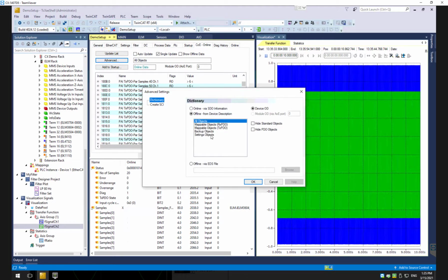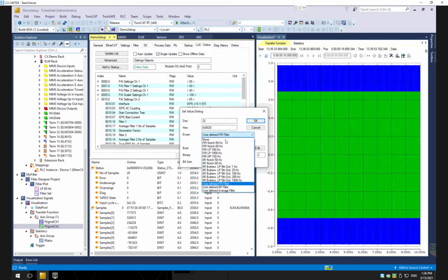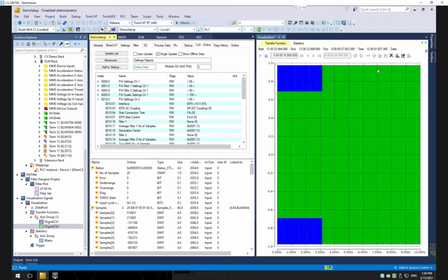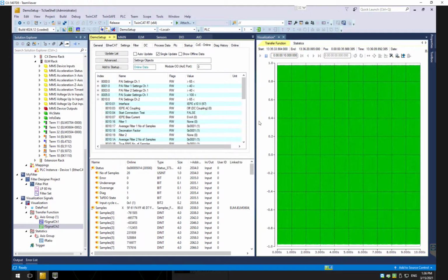We'll then go to the second channel and set the actual filter, which is now set to user defined, to 0, no filtering, and immediately channel 2 also goes up to the full value because it's not filtered. And as soon as I step back, of course, the output will drop to the 70%, and we can also do more checks on this.